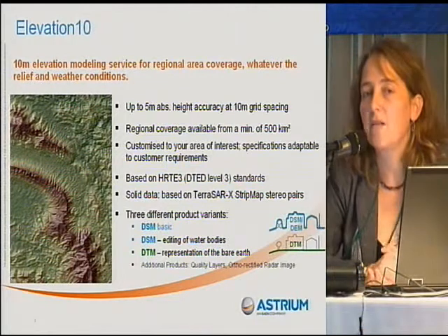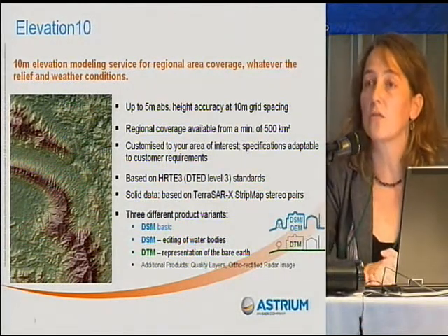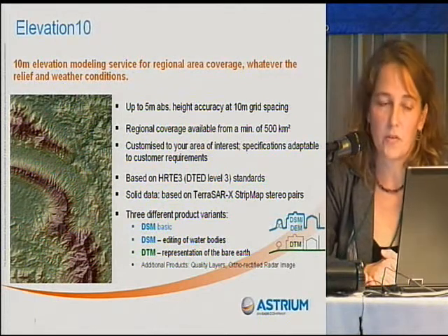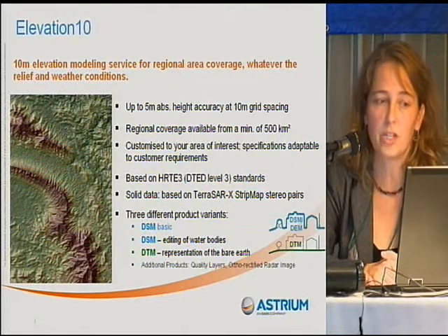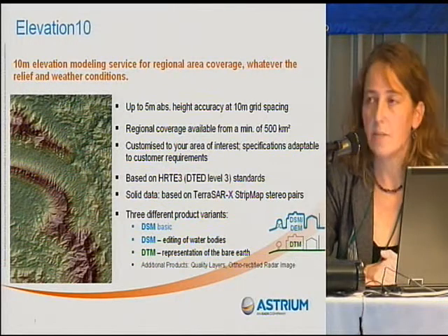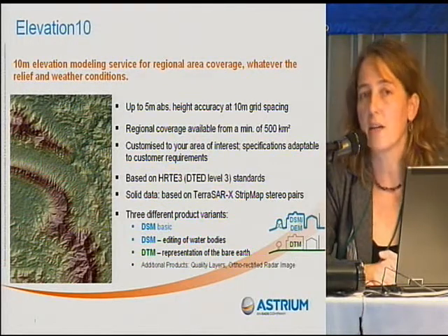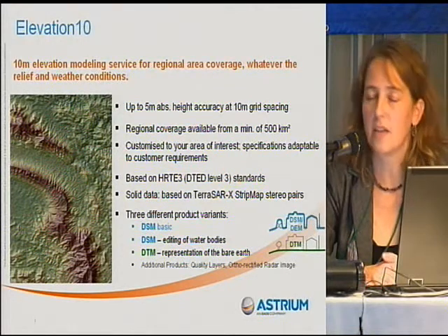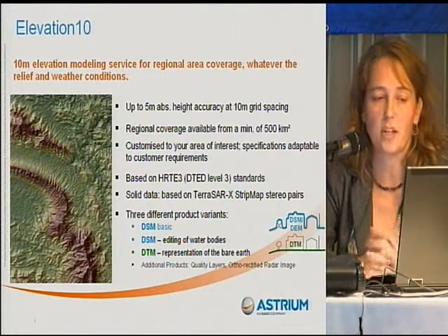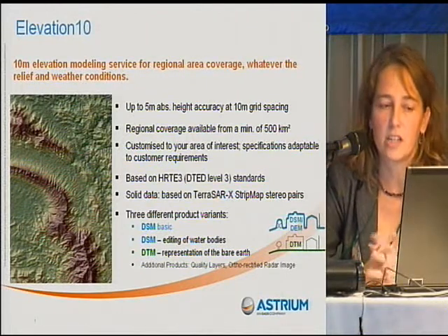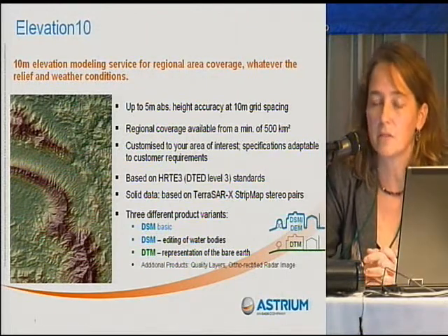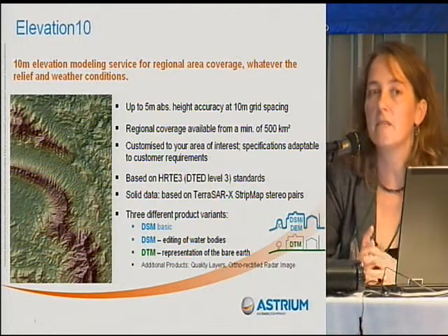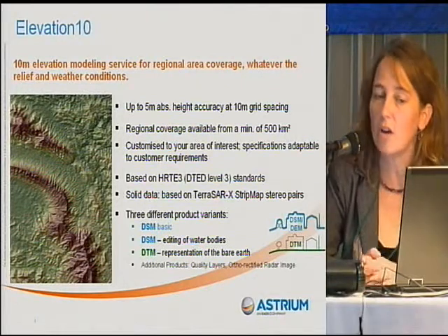The next product we have is the Elevation 10 product. This is based on radar data, on the TerraSAR-X data, using radargrammetry technology for that. 10 meter grid spacing is already mentioned, and an absolute height accuracy down to 5 meter. And this is a product of the HRTE3 or DTED level 3 type. In this case, we are offering 3 different product variants, we call it.